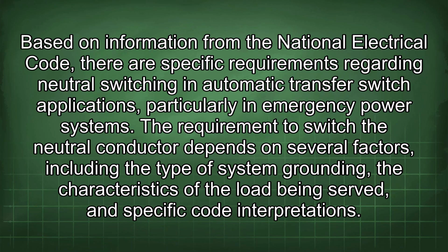Based on information from the National Electrical Code, there are specific requirements regarding neutral switching in automatic transfer switch applications, particularly in emergency power systems. The requirement to switch the neutral conductor depends on several factors, including the type of system grounding, the characteristics of the load being served, and specific code interpretations.